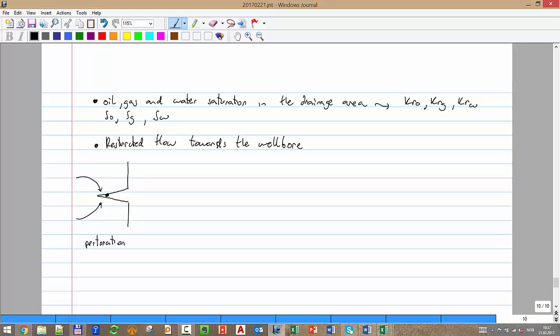Okay. We also have, for example, we drill our well and some part gets invaded by drilling mud. So the flow here will have certain characteristics, but when it flows through the mud it might damage the formation and the flow will be impaired. So that's mud damage.